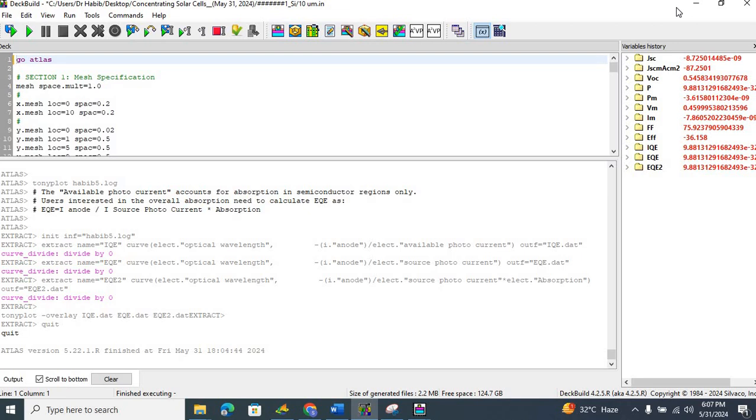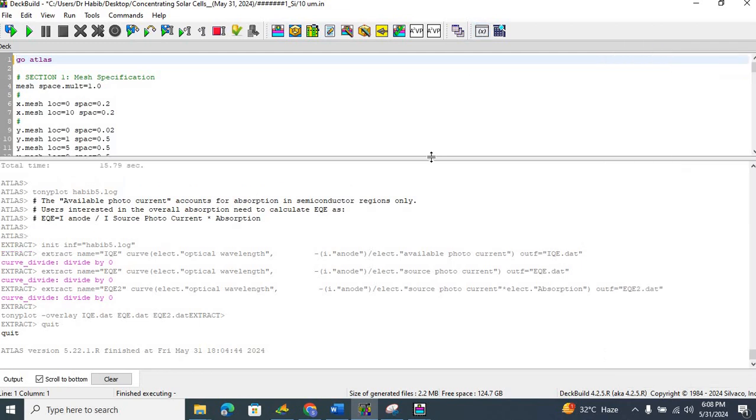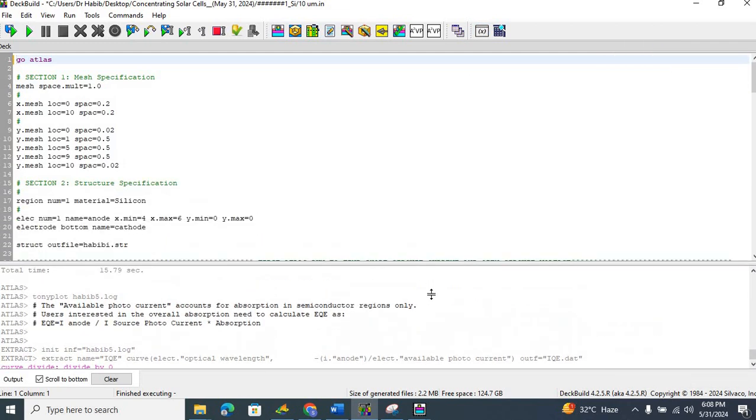We have to cool down the solar cell in order to have a reasonable efficiency. So in an actual setup, we don't really get these high numbers, especially for a light intensity which is 2 times the AM 1.5 conditions, but still this simulation gives us a good idea of concentrator photovoltaics.